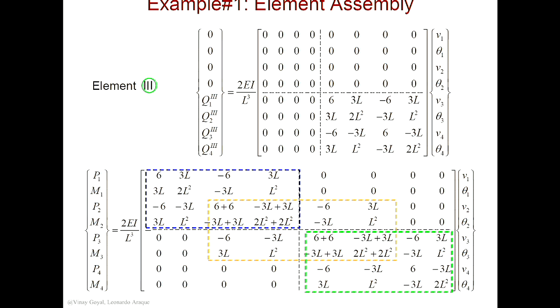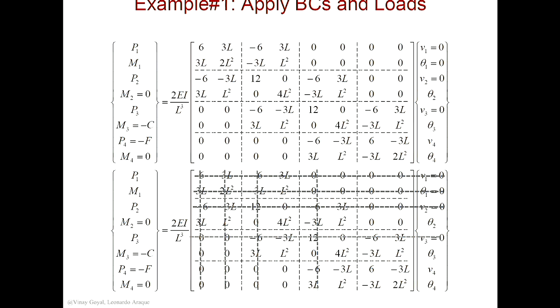So now I'll impose the boundary conditions. That's the next step. When I impose the boundary conditions, I know on the left-hand side, remember it was clamped? Yes? So if it's clamped, then V and theta are 0. Then, I don't know if you recall, but in that next node, I had a pin condition. Is everybody with me here? So then that's 0. And if you recall, the next node over, also I had it fixed vertically, remember? So I imposed those boundary conditions. And on the left-hand side, because these are imposed, these must be reaction forces. They have to be. And if you recall, in node 2, did I apply any moment? I didn't apply anything.